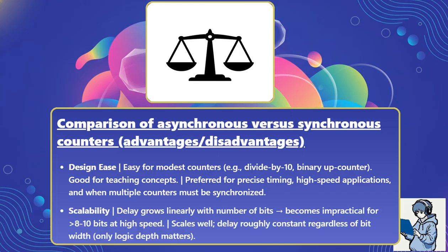Scalability. Asynchronous counter delay grows linearly with the number of bits, becoming impractical for more than 8 to 10 bits at high speed. A synchronous counter scales well. Its delay is roughly constant regardless of bit width, depending only on logic depth.